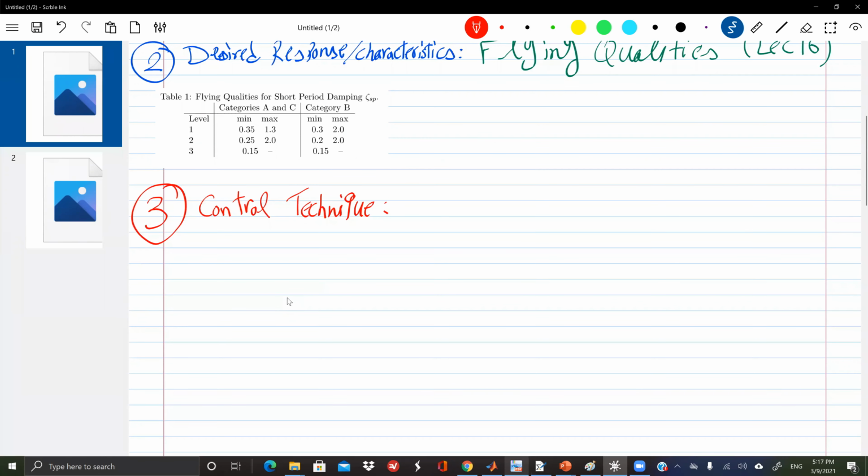All right, so here we do state feedback, which is quite powerful if you can do it. So we do pole placement, which is our control law. The law that governs the input you provide every time step is that your input is given by negative K as a matrix times x as a column.